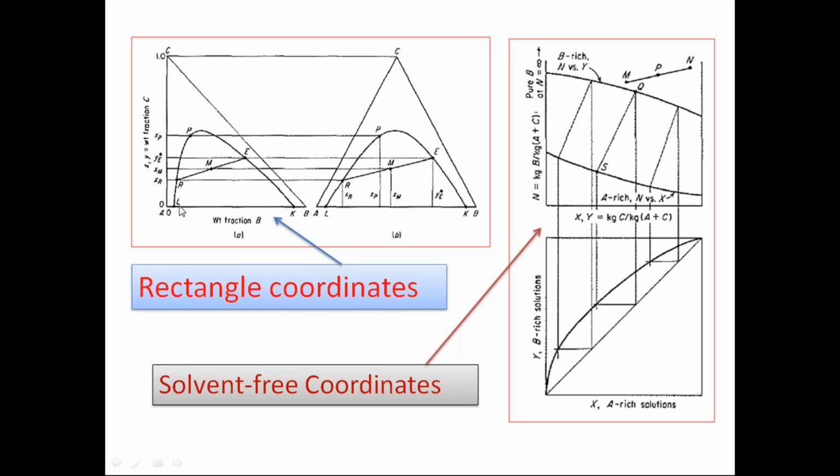So N may be there in the raffinate phase. So the raffinate phase N values will give a curve like this. And in the organic phase, because the weight of B will be more, you will get this type of curve. So this is the N in the organic phase. This is N in the aqueous phase. So N in the aqueous phase versus the other X value. What is the X value? X value is the weight fraction of the solute on a solvent-free basis.